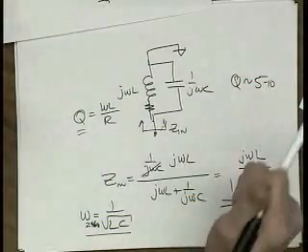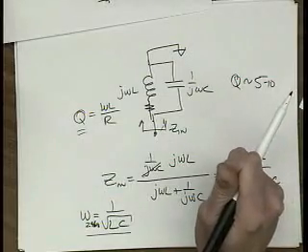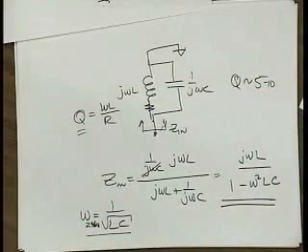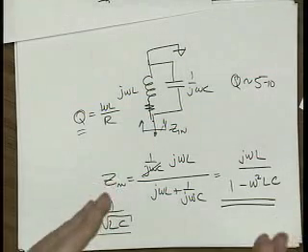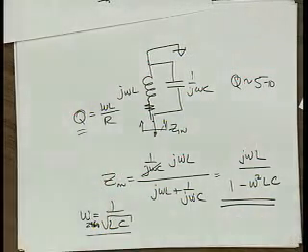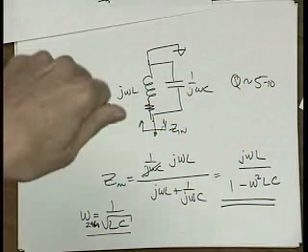Right now, to buy a radio that works at 60 gigahertz would cost you like $10,000, because they use indium phosphide. They use these exotic materials. Right now, as we speak, all of a sudden, CMOS at 130 and 90 nanometer became able to do what people forever had to spend thousands and thousands of dollars to do. Pretty interesting. I mean, here's a big opportunity. That's why it's a research project for us. Radars on cars. Future cars are going to have radars on them. There's going to be radars for cruise control. They'll put a radar in front.